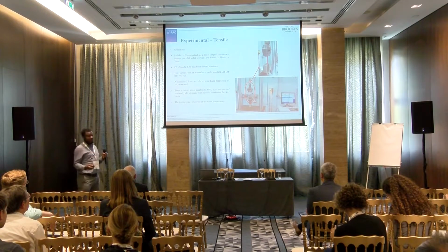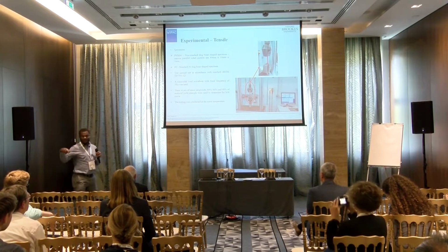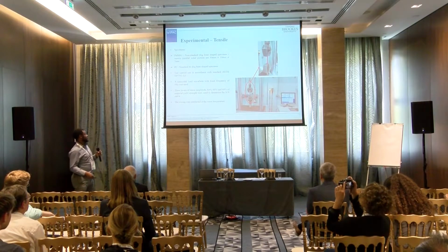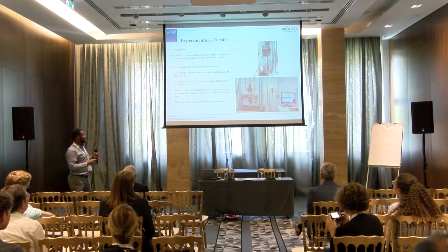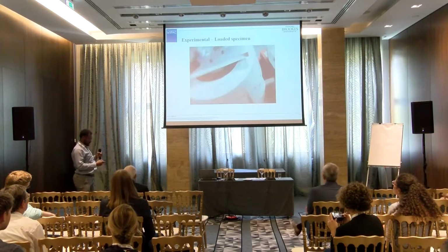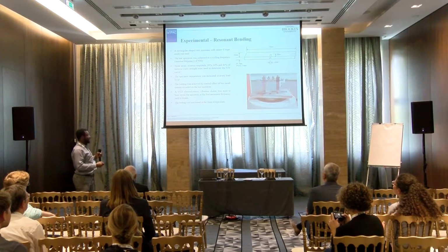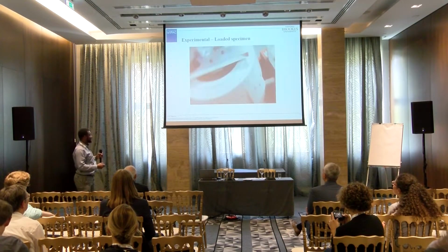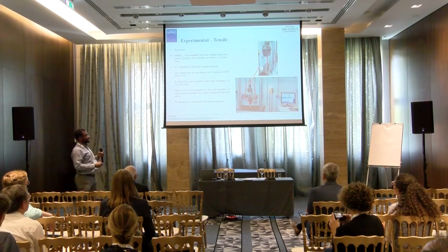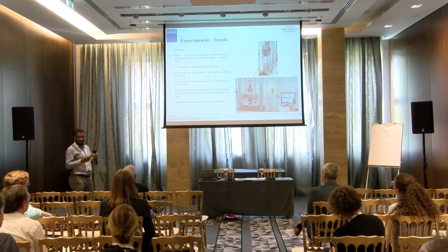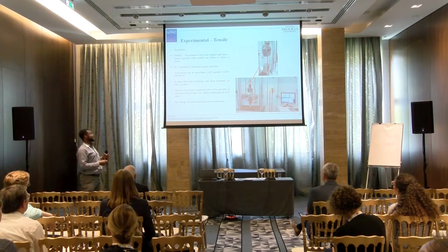We did the tensile test to compare it with our new test setup. And the specimen is PMMA. That's what we use to validate the system, the tensile test. So here is the loaded specimen, and that is a static jaw. This is the moving jaw. That jaw moves at 5 Hz frequency, okay? And then keeps on pulling it until the material fails.